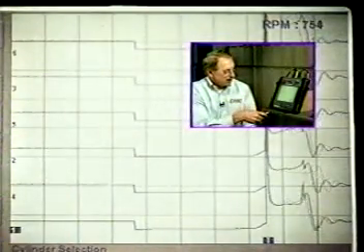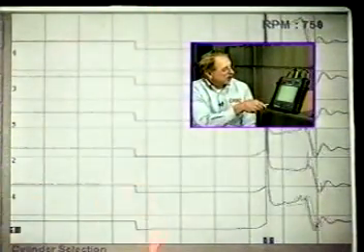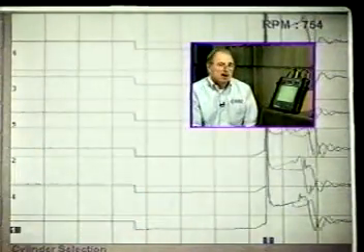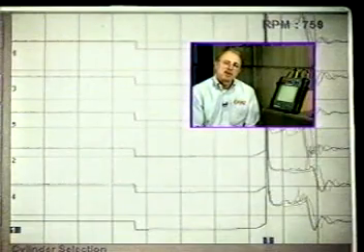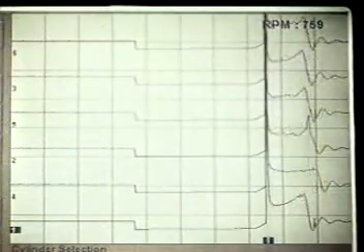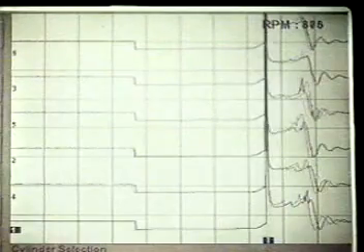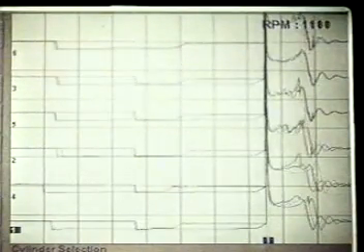Now, what you're looking at here, focusing on the point of primary turn on in the primary dwell section, you will notice the alignment. As you recall, on the DI presentation, we told you that they will never be perfectly lined up, and the maximum variance that you should see when comparing cylinder to cylinder is a maximum of 500 microseconds, which is typically 1/2 of 1 millisecond. You can see we have that. But let's bring it off idle up to about 1,000 RPM and make sure that we don't have any massive dwell variation problems.